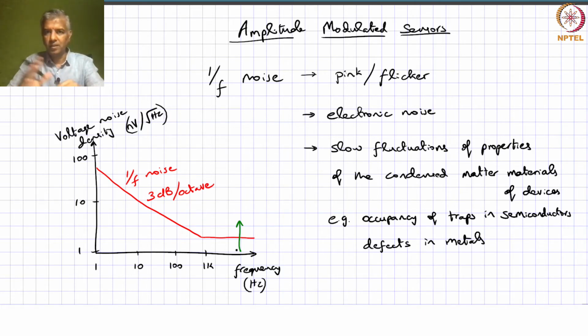Instead of making a static measurement where you send some uniform intensity into your gas cell, you could actually send modulated light, okay, and then do this detection, and then of course you can demodulate that light and move our measurement back to the DC and extract our signals.